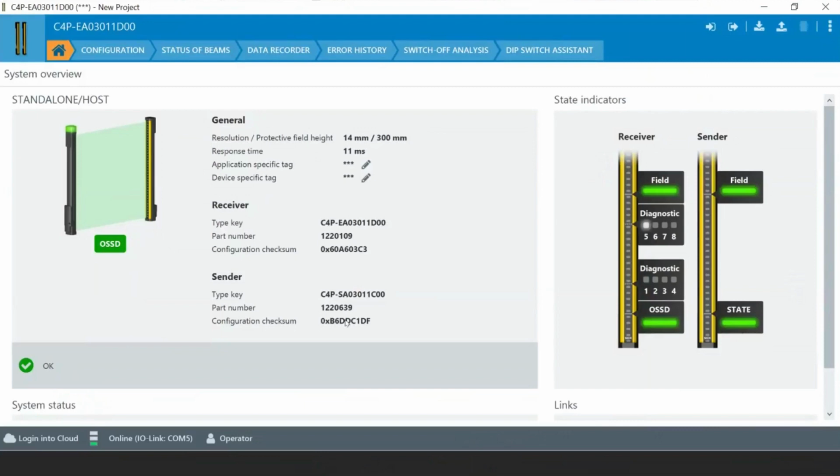Okay, perfect. So what we have set up here is a SICK DTEC4 light curtain. And what I wanted to show is that IO-Link can be used even on safety devices. So what we're getting here is just a quick view of the DTEC4 and its current status. We're using the Sophos engineering tool to connect to the light curtain over IO-Link. And this is something that traditionally has not been possible in the marketplace. SICK recently released this functionality into the DTEC4, and it's great for doing configurations and diagnostic work on your light